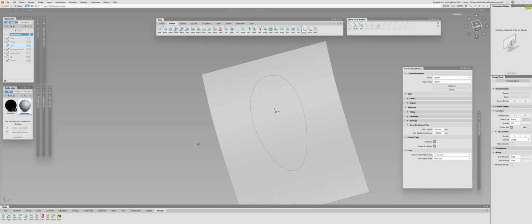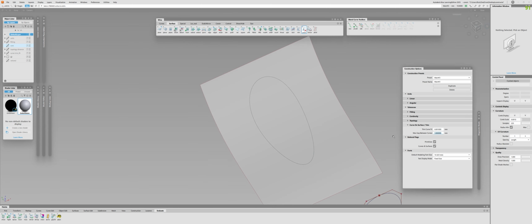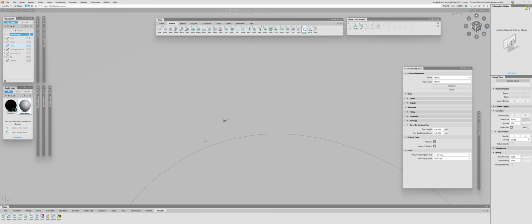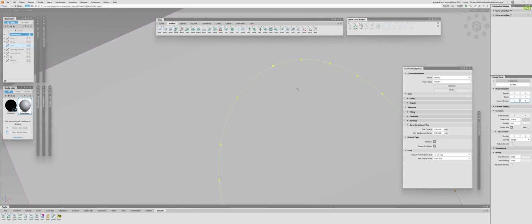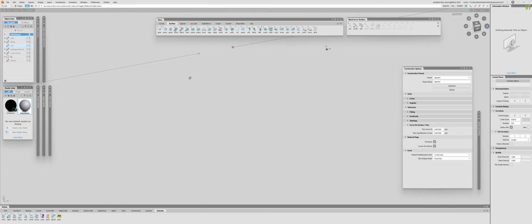If you say, well, that's so awesome, there is nothing awesome in that, because of what Alias will do with the looser tolerance, which I suppose it was never supposed to do. I don't know why Alias leaves it as an option. Because when we have this gap, Alias will automatically create a curve and surface, just a straight line, and connect that without bothering about any continuity.